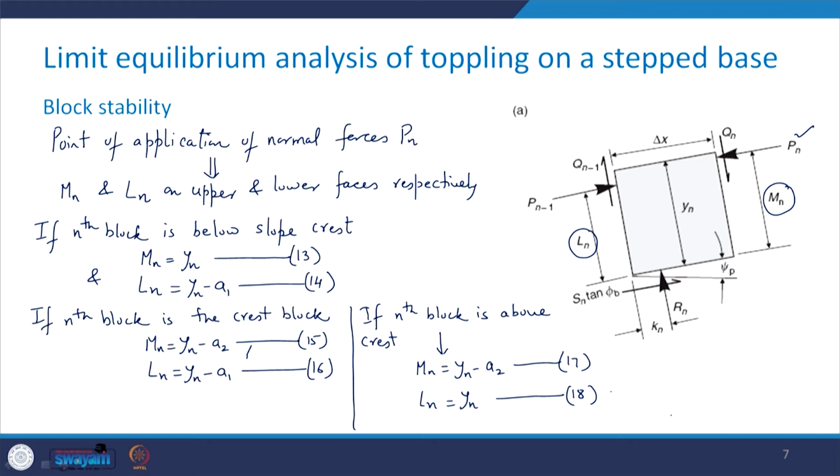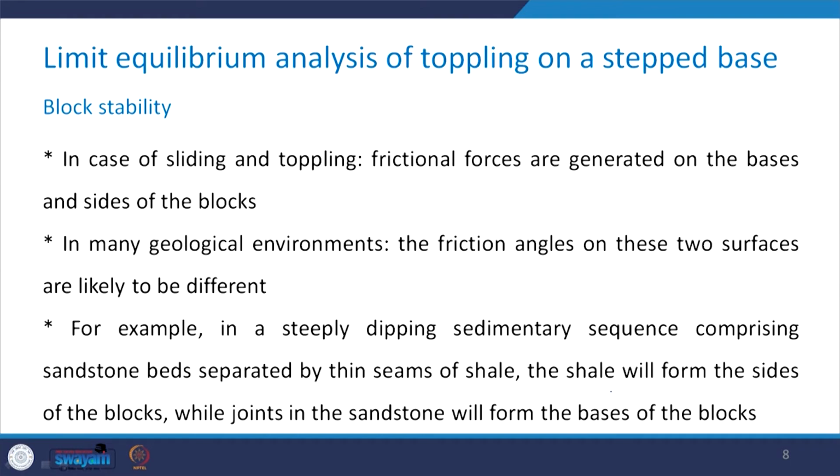Now, in case of sliding and toppling, frictional forces are generated on the bases as well as on the sides of the blocks. In many geological environments, the friction angles on these two surfaces are going to be different. For example, take a steeply dipping sedimentary sequence comprising sandstone beds separated by thin seams of shale.